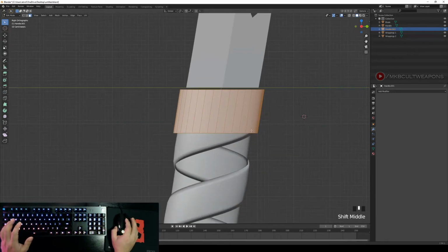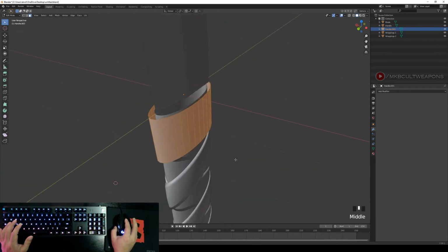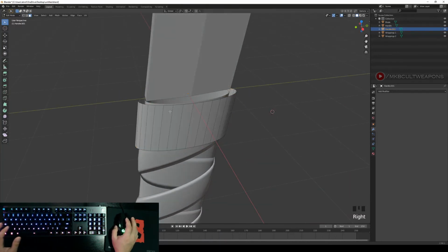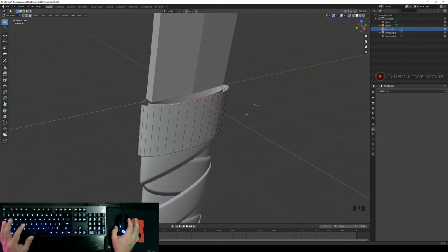Okay, I guess this is perfect. Yep, we just need to extend it a little bit. Shift Alt, select, let's do that again. Go to edge selection, Shift Alt, then select the top part to select everything on the top, and try to press F to fill that gaps, and you press